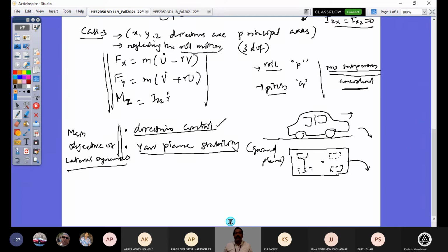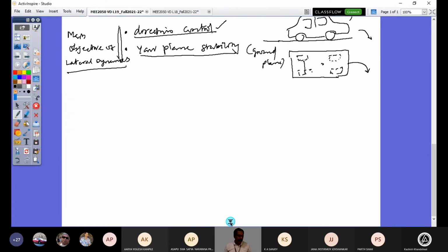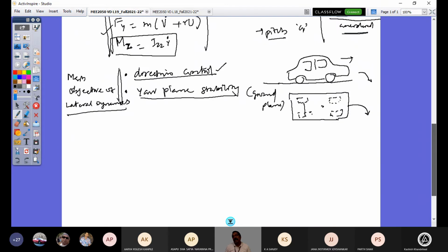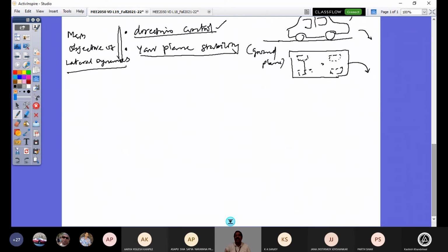If that is the objective, yesterday's Newton-Euler equation, the very long equation of moment, is reduced to a simple moment equation. Only one equation is sufficient, and the two simple force equations. So this is the beauty of your dynamic governing equations for your lateral dynamics study. And in this, I can simplify further. I require one simple equation, ultimately, to say the characteristic of a vehicle.